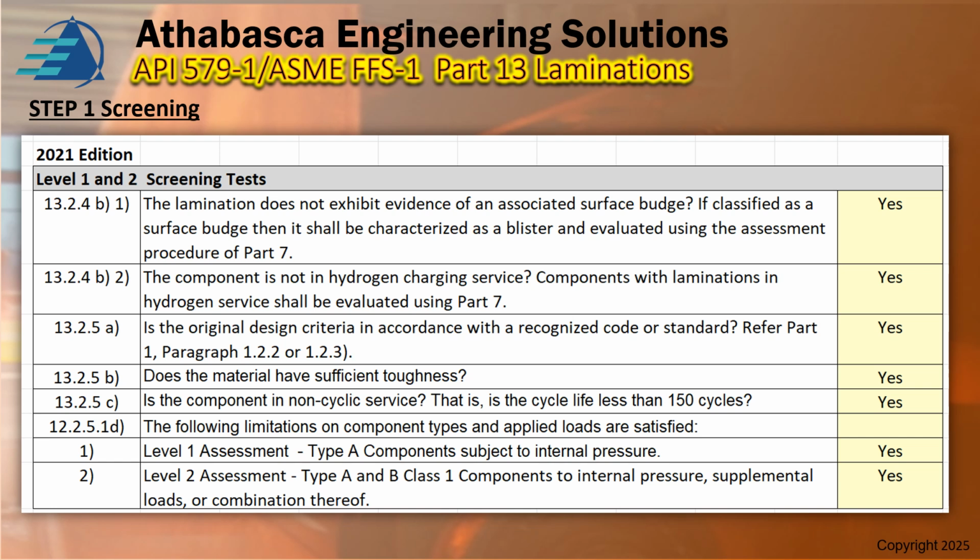Lamination does not exhibit evidence of an associated surface bulge. That's associated with hydrogen charging, and in other sections we have the effects of hydrogen and blistering.